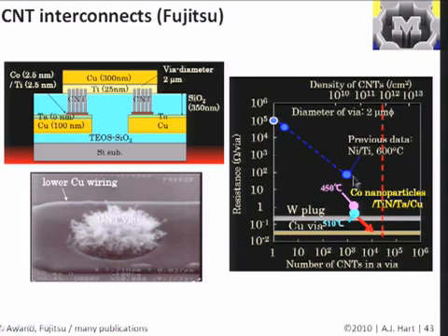There's still a long way to go in understanding how to control the growth process and how to couple it with all the other manufacturing methods, which is one of the big challenges to integrating nanotubes in devices like circuits. You can certainly grow better nanotubes if you grow them on their own, but you can't grow them so well if you confine the growth to these small holes and try to decrease the growth temperature to be compatible with the roughly 500 C limit that exists for the other materials needed to make the chip.